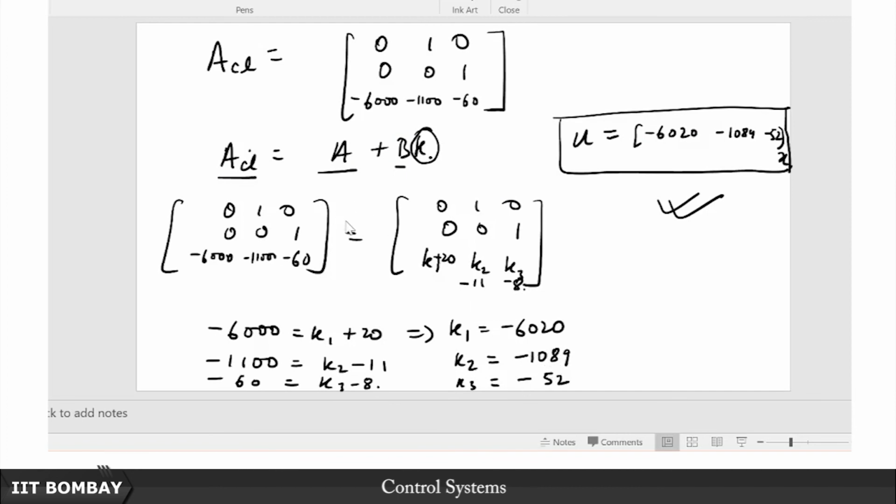So there we will have to equate the closed loop characteristic polynomial, and because the observer and controller design processes are just duals of one another, very simple, except that A plus BK there, you have A plus LC here. You can look at it as A transpose plus C transpose L transpose if you like, either way it is just the same. The only thing is that you need to be able to represent it in the observer canonical form.